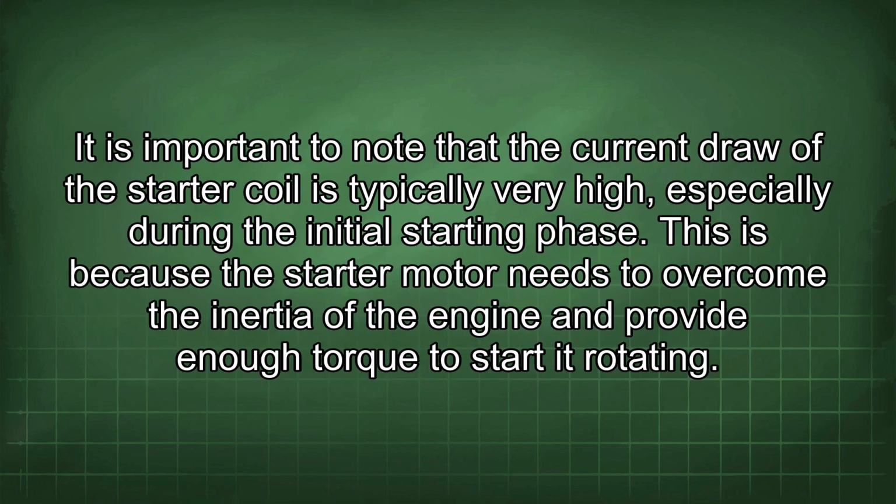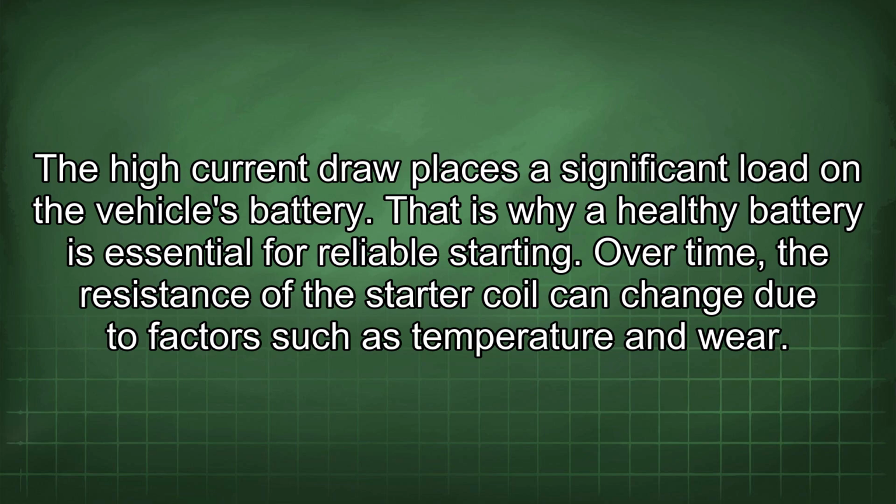It is important to note that the current draw of the starter coil is typically very high, especially during the initial starting phase. This is because the starter motor needs to overcome the inertia of the engine and provide enough torque to start it rotating. The high current draw places a significant load on the vehicle's battery. That is why a healthy battery is essential for reliable starting.